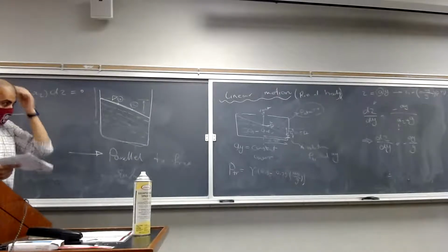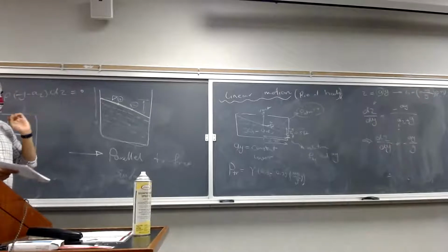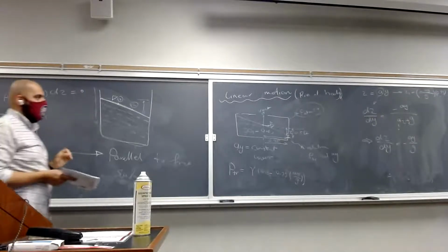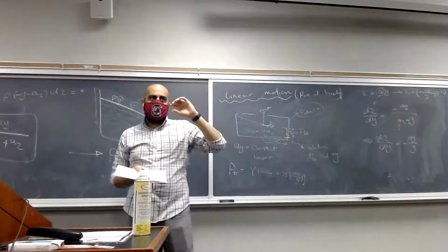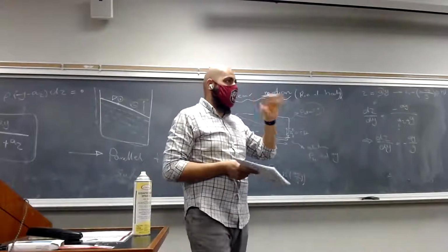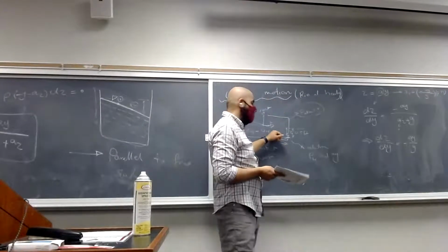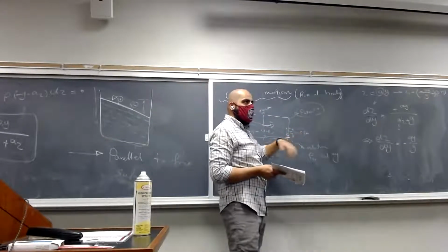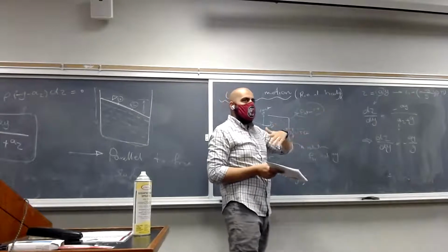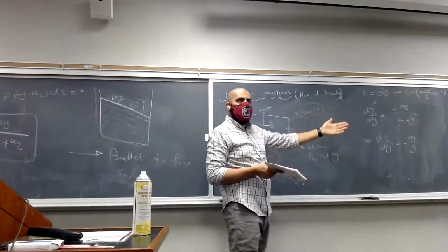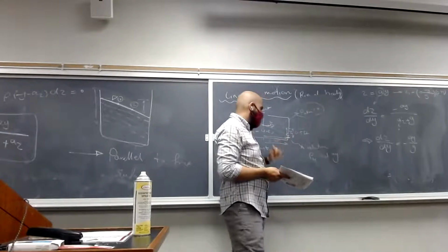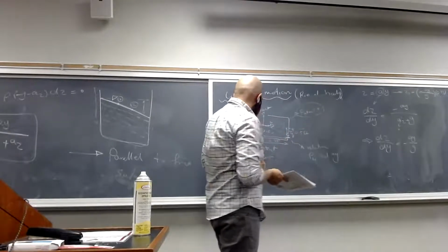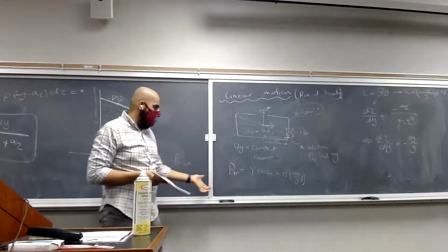But we want to find the maximum acceleration that is going to cause the water level to drop below the transducer. So we essentially are looking at a value at which the free surface is on the transducer. Whatever value we get higher than that is going to be causing the water level to drop below the transducer, okay? How can we find that based on this equation?